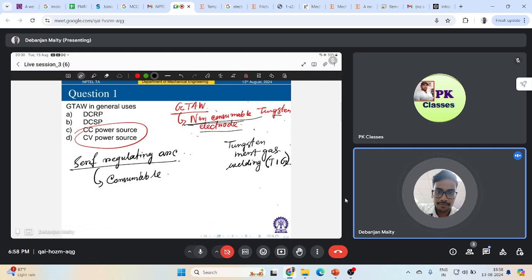In the semi-automatic arc welding process, the arc is maintained between the workpiece and your wire, which is driven forward at constant speed. There will be some spool to which you continuously feed your electrode, and then you'll have some welding torch, and you'll melt it through arc, and then you'll have the workpiece, right?